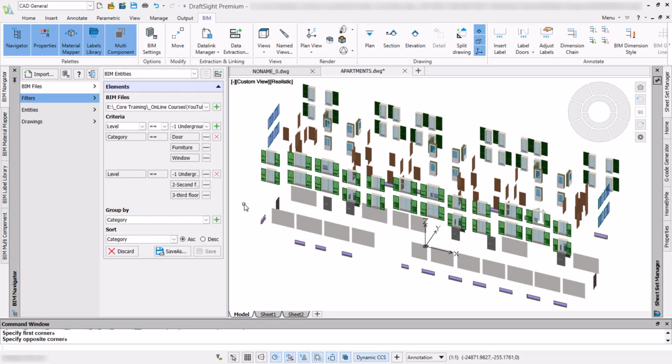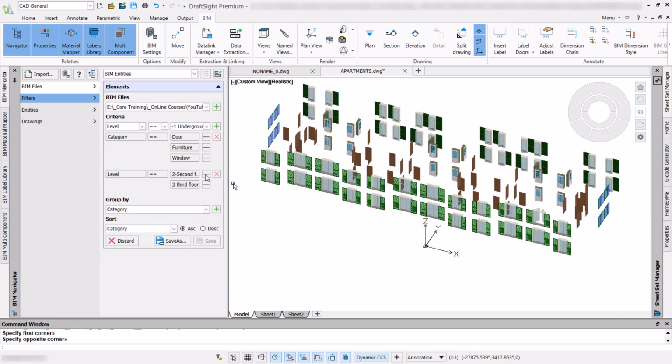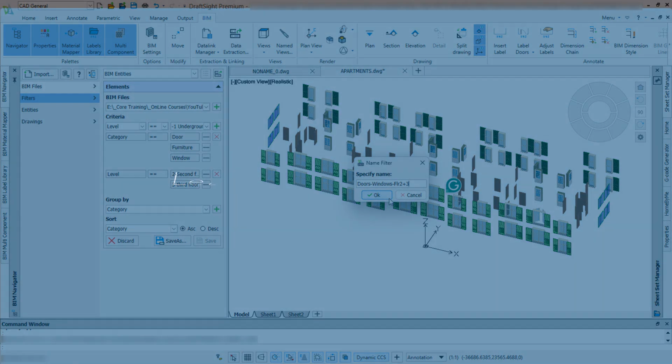Filters reduce the design content shown in the graphics area to just those aspects that we want to review. This limits the drawing entities and the information included in data extracts, so that it is possible to easily obtain precision lists. Please note that these are preliminary steps. In the following video, we will use tools to generate plans, sections and elevations, as well as apply materials to enhance the drawing detailing. So, let's get started.